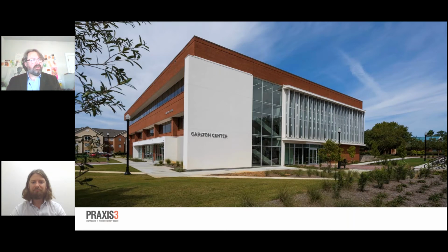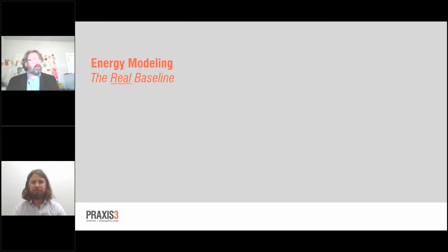And here's the Carlton Center that we looked at earlier from a different angle. You can see this is an east facing facade. So these vertical sunshades help us in that mid to late morning when the sun is moving around toward the left of the image, and creates some learning spaces behind that get really nice diffuse light for most of the school day. And it's a really, really nice space. And by focusing on that area as opposed to all of those brick areas, we were able to get not only some good energy performance, but also some quality of life performance there.